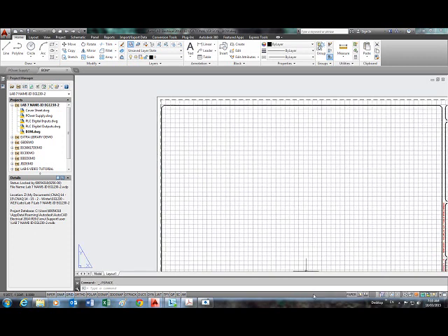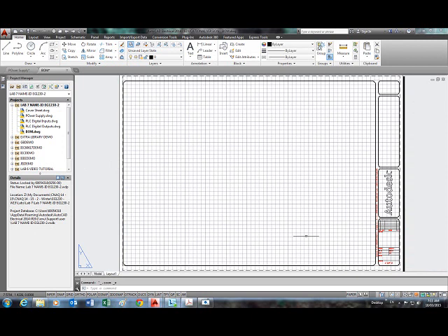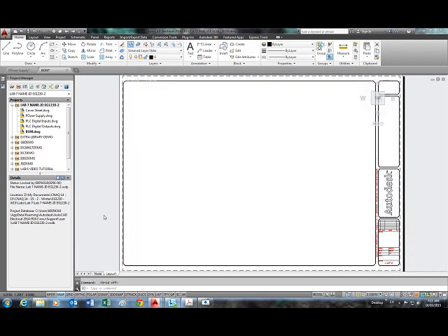Let's go back to paper space, double click the wheel to zoom extend, again model space, turn off the grid, nav cube off, and save. Go paper space again if you want.